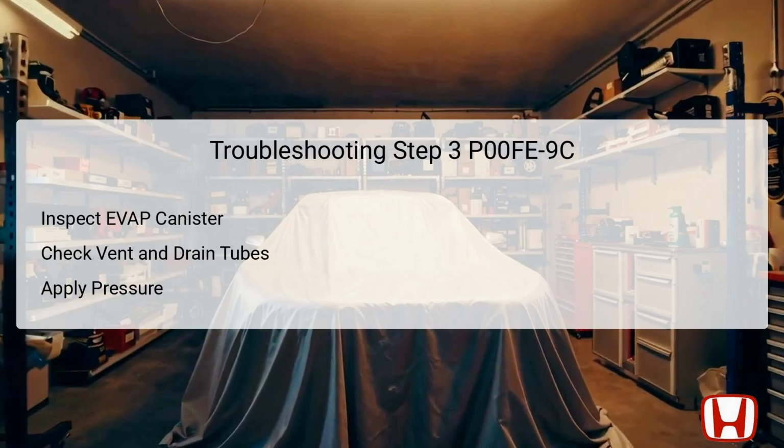During the third troubleshooting step, attention shifts to the EVAP canister. Disconnect the fuel vent tube as well as the drain tube from the EVAP canister. This isolation allows for a more effective assessment of blockages. Connect the vacuum pump to the drain tube port to begin testing.